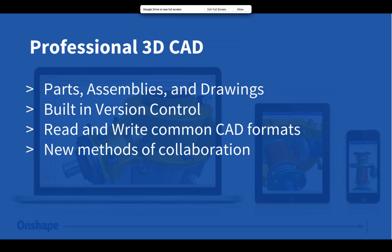Now, some other things I'd like to highlight is with Onshape, we have built-in version control. And this is very important for the topic of today because we don't have to have a separate data management system to manage our files. There are no files in Onshape, and we can manage versions within the document. And this is a neat capability because, again, in a traditional CAD system, that often involves a PDM system with separate software, a separate management application. It's oftentimes very expensive. The idea behind Onshape was we wanted to have version control built into the core.